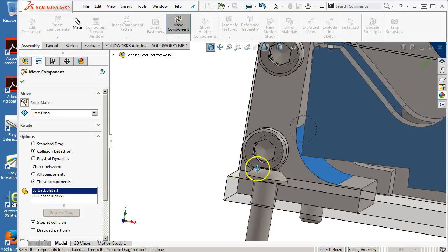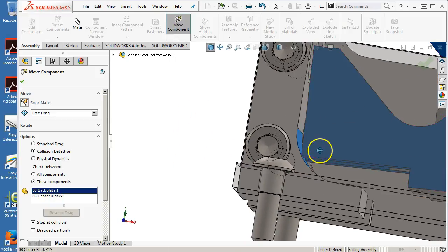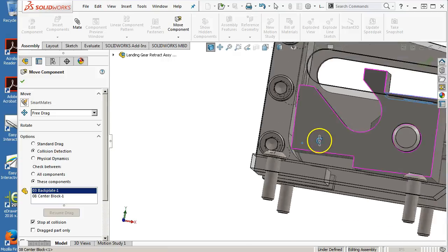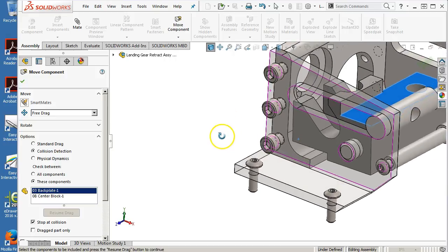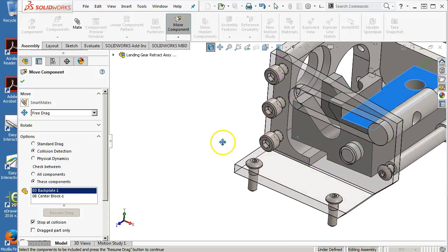Now if that's acting as a stop, that may be okay. At that point, that may be the stop from keeping it going too far. Unless it jams in there. But yeah, unless we gall it and actually manage to lock it in place.